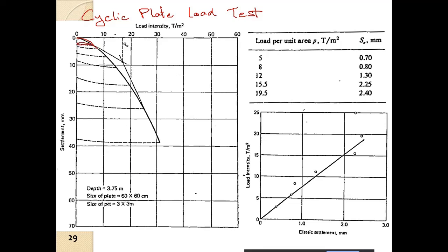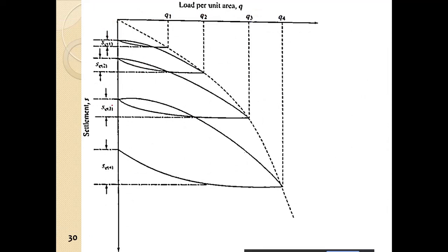Then again loaded up to this point and released. Then loaded up to this point and released. In the cyclic plate load test, if we consider this one, we have a total deformation, and this is the corresponding load.